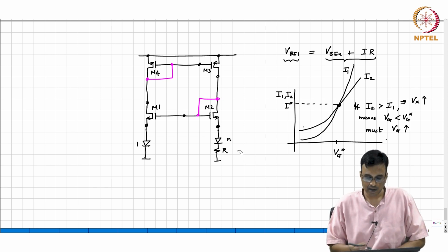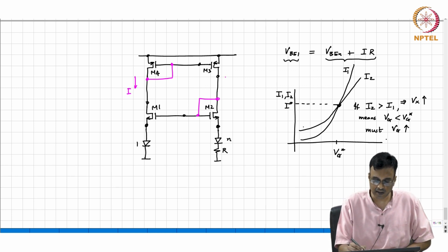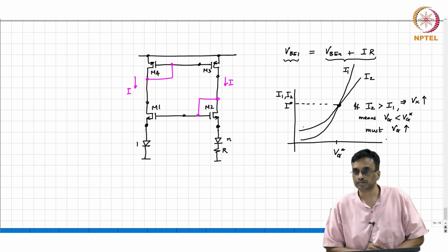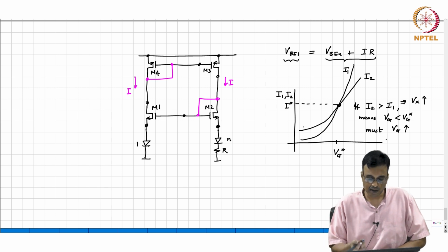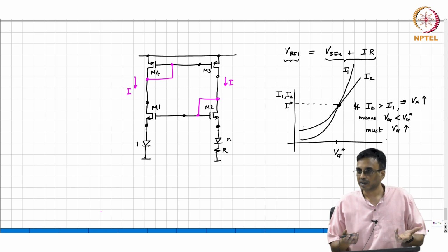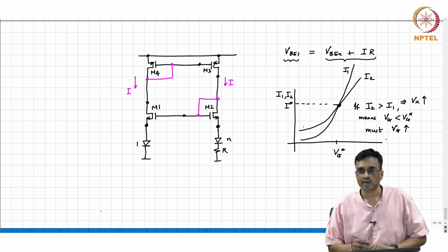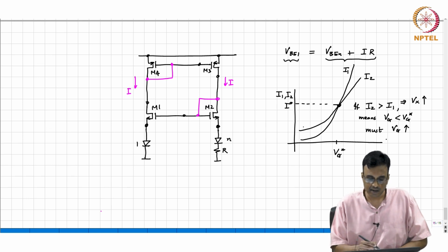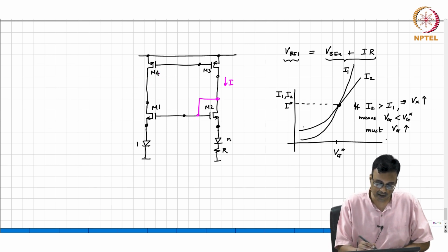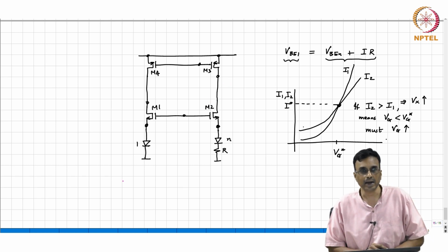You would go through the equations, which are still the same; the current flows. If you assume this is I and this is I, you apply KVL across the same loop. So it appears as if it makes no difference whether you mirror this way or that way. It turns out that if you analyze it carefully, this way of doing it is basically positive feedback, right?